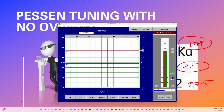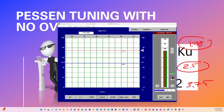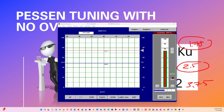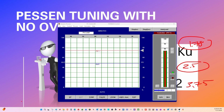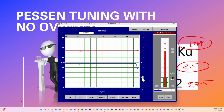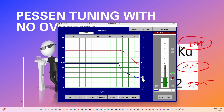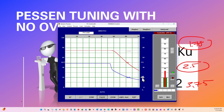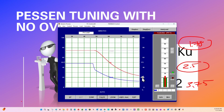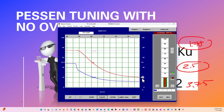You might recall that when we did the Ziegler-Nichols loop tuning, we said that if it is too aggressive, sometimes just half the gain and twice the integral is going to give you exactly what you're looking for. So I've just gone for 1/8 of the gain and twice the integral. I have put that in, and now you can see the response that we are trying to achieve. I'm going to take the set point down to quite a low value, and as you can see, there's no overshoot. It's going to ease in quite nicely. And if I was to go in the opposite direction, I should have the same effect.